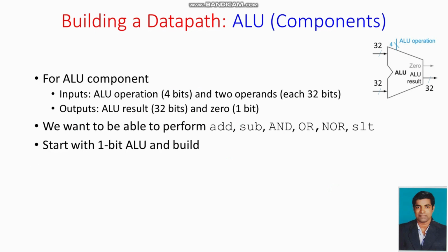We want to be able to perform add, sub, and, or, nor, set less than. Start with a 1 bit ALU and build. Logic and arithmetic include full adders.